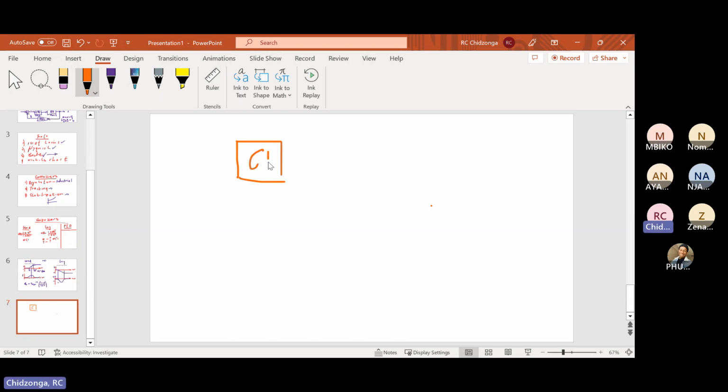I'm not drawing the full block diagram now. I'm just drawing the portion where the controller has an input E, which is the error, and the output from the controller is the signal U(t), which we call the actuating signal, right? So in other words, your U is simply the controller transfer function times the error, right? Like this. This is your output from the controller.